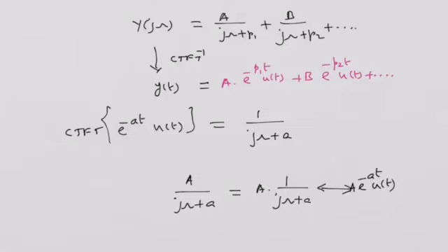So the transfer function is defined with 0 initial conditions. There is a possibility for you to obtain the response in the time domain, or let me call this response the steady state response. What do you mean by steady state response? It is the response generated with 0 initial conditions, or it is called by the name of forced response. Only the steady state response or forced response can be computed via the frequency domain.